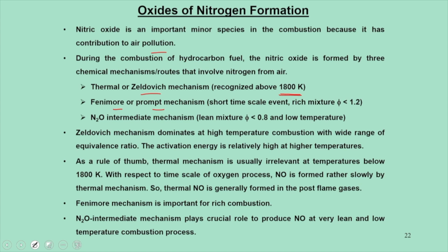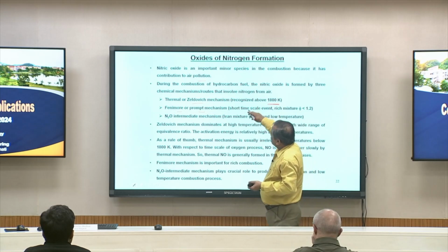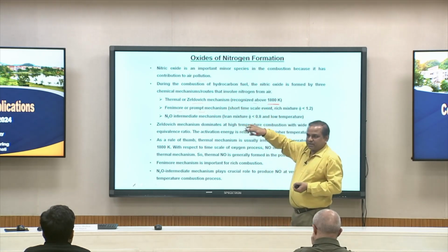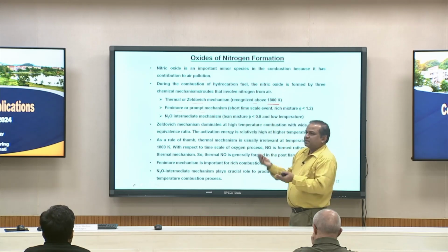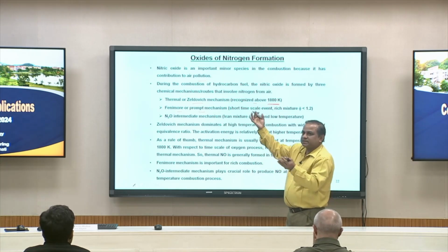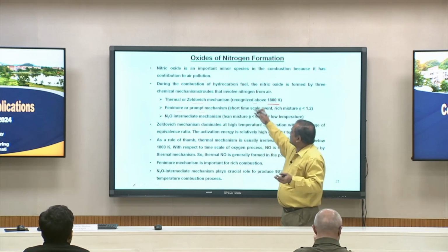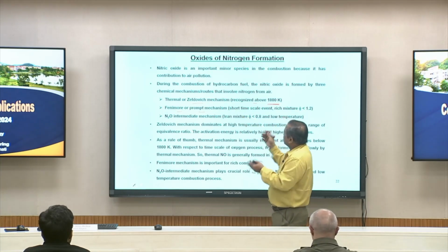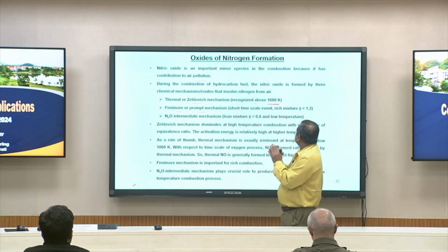That's the reason when you simply ignite, initially for a short time you may see NO, after that it vanishes, because the Zeldovich mechanism dominates. Initially the temperature rises fast and NO starts forming, but it suddenly sees high temperature, so this mechanism dominates. That is why, when you look at that reaction in a very short time scale, this is true.